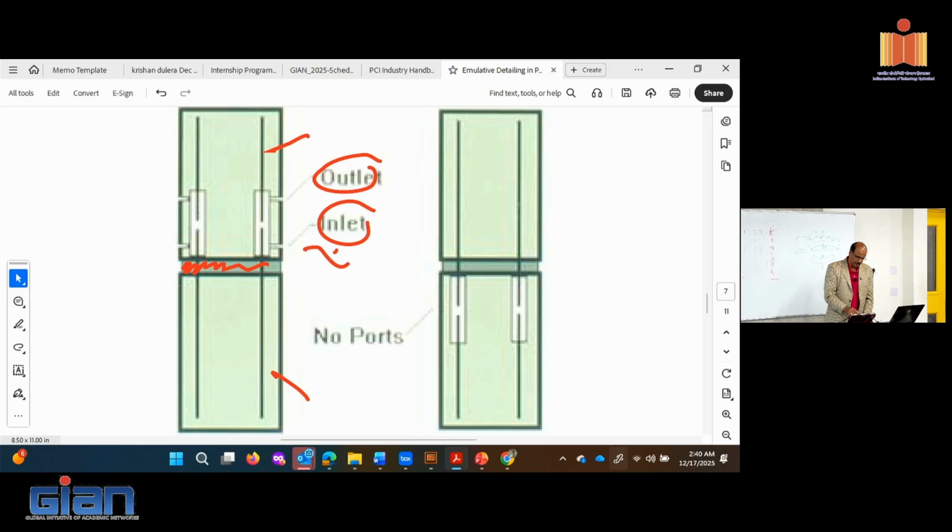So typically they will pump from the bottom. Why do you think they pump from the bottom? To push the air out. So they will pump from the bottom until the grout comes out of the top. Typically they use a pressure grout, non-shrink pressure grout. Sometimes they will mix it with some fibers to provide strength depending on the size of the couplers. So it's a fairly standard detail people use now to do it.